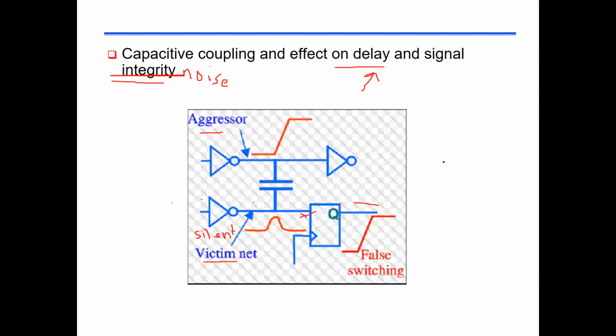What happens is exactly what happens when you have two racing cars. Okay, so if you have two racing cars, or one standby car and one zooming car, the zooming car's speed is going to affect this standby car and shake it. Okay, so in coupling, if I have two wires here, naturally there is an interwire capacitance between them, C, that we call coupling